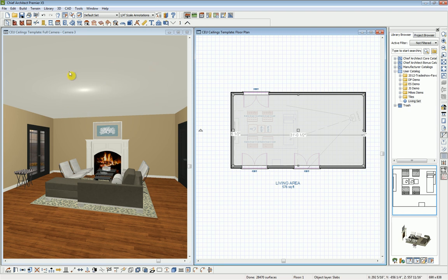and the next thing we want to do is cut a hole in that slab that enables us to create our tray and then eventually our coffer. So with this slab already selected, I'm going to go down to our edit tools and copy and paste it in place. And I'm going to go up to my corner, and holding the C key down, the letter C, it's going to concentrically make that move. So I can pull that out and kind of dimension wherever I'd like that to be. That looks pretty good to me. I'll release my mouse. So that has made a copy of that and placed it in place.